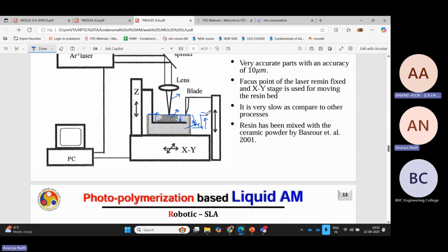It goes extra down one more layer, and then one move more up. The extra layer will come after it goes down and comes back. Okay. So in the case of deep dipping, if you are going just one layer thickness down, then you need to understand the reason also. It takes more time because the layer is just 20 or 30 micron. So that's why we do this.